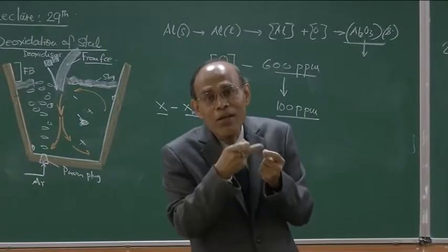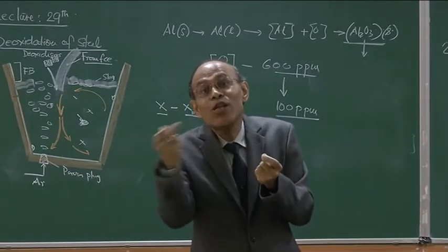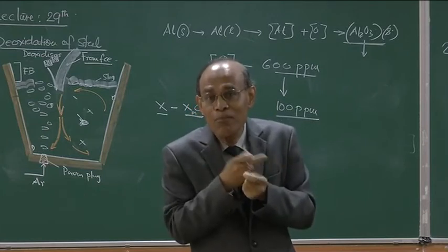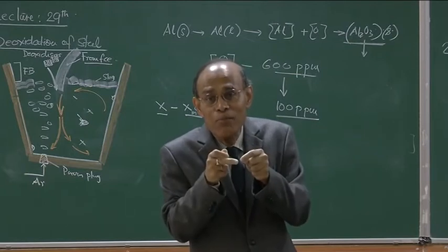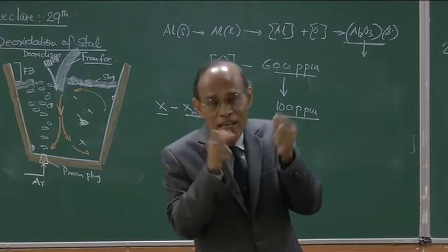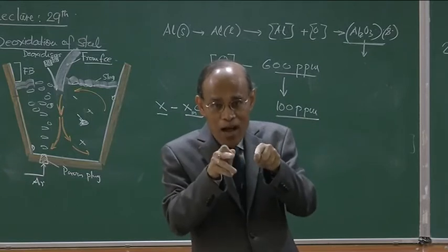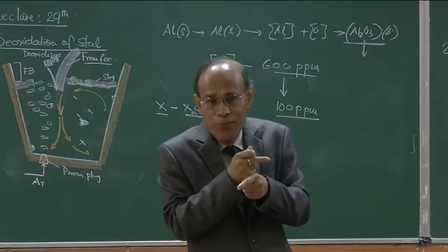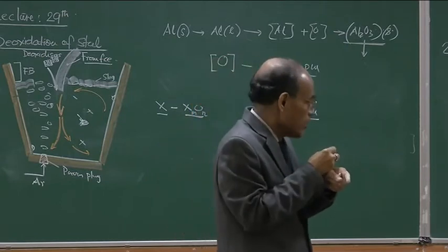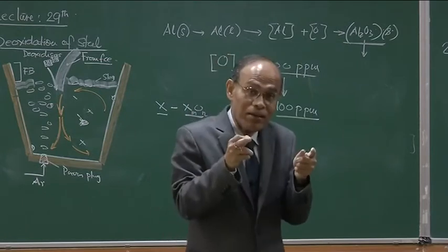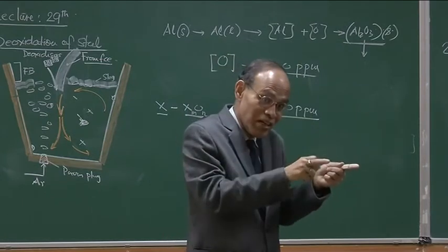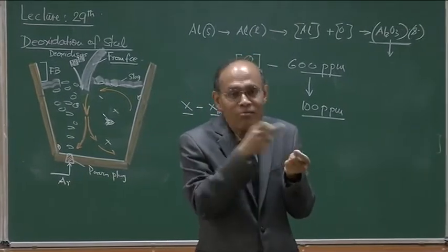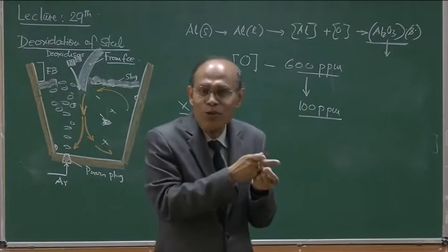You can use ferrosilicon, ferromanganese, or silicomanganese, and I would like to use silicomanganese in such cases, because the activity of silica and MnO are going to be reduced, and I will be moving towards a lower residual content of the deoxidizer element in the steel. So I will prefer silicomanganese as opposed to silicon, because I will get to the same level of oxygen no matter whether I use manganese, silicomanganese or ferrosilicon.